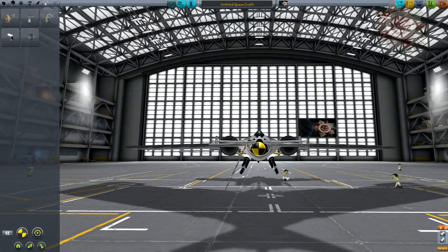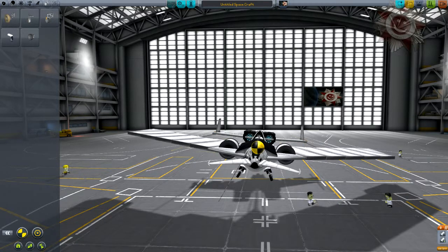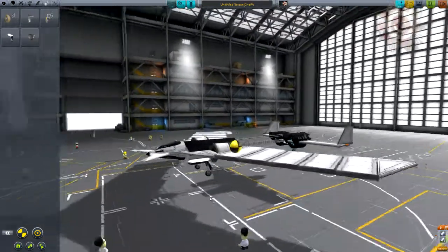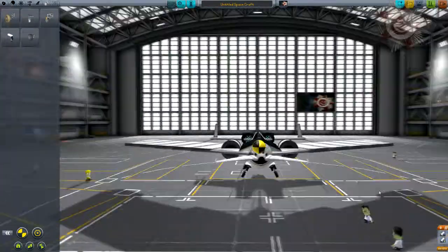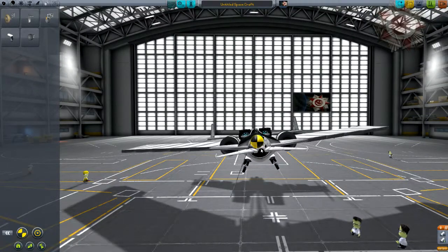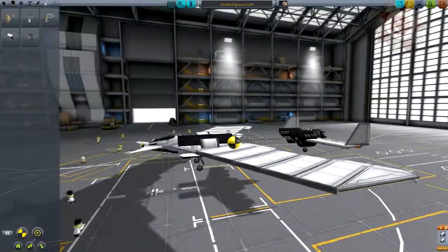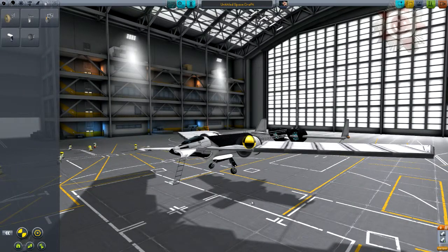Only two wheels touching the runway, it becomes more unstable, and if it rolls to either side, only one wheel will be touching the runway, and that's a very unstable position. So we will need to lift off before that roll happens. We have so much wing that I think we can lift off at really slow speed, but we'll see.